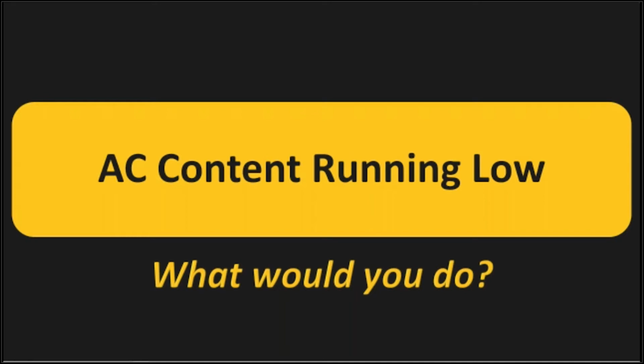What's your response, buddy? Dude, if we're 0.5% low, and this is just us, everybody's making their own decision, but if we're 0.5% down, it's like, stop. Stop shipping, figure out what's going on. That's a huge drop. Day-to-day we're normally looking at a 0.2 or 0.3 drop. You don't really know what to do unless you check your gradation. So it's very important to get another burn right away.